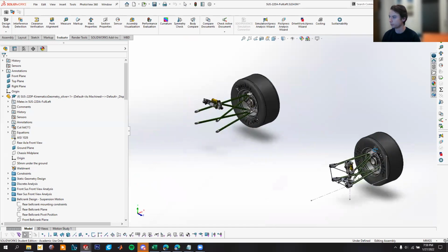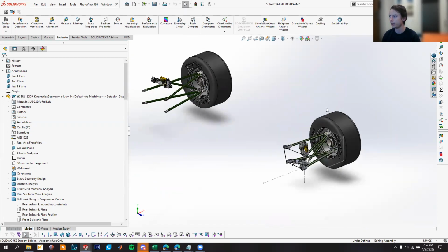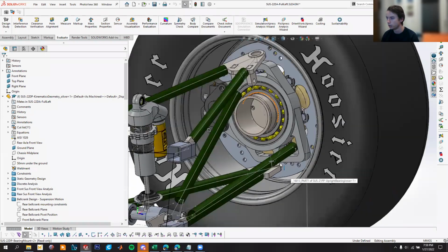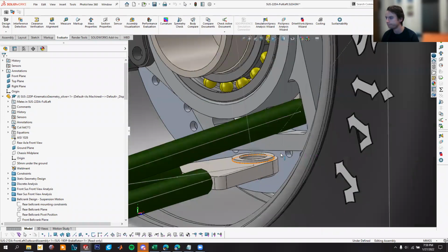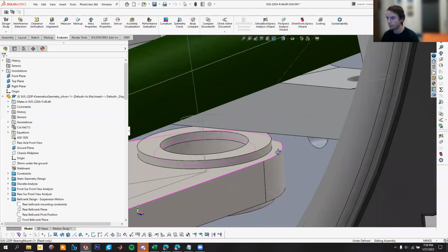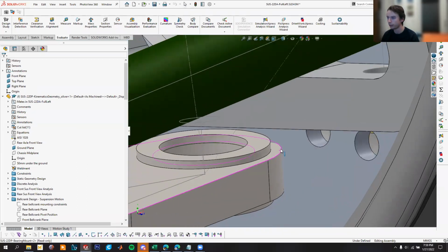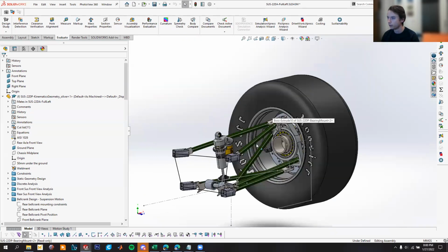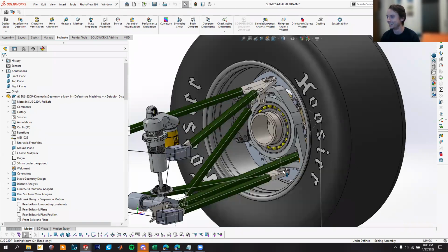So the suspension has passed its test of clearing the wheel shell. The one thing we caught was the lower control arm having a millimeter and a half of interference with the brake rotor. Even if we didn't catch that, the brake rotor would have fixed it for us.